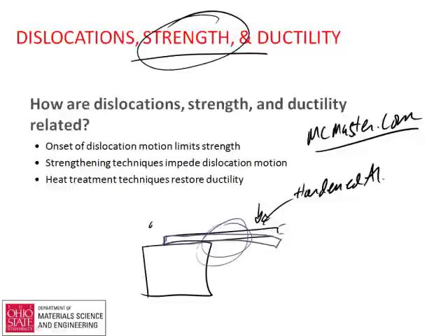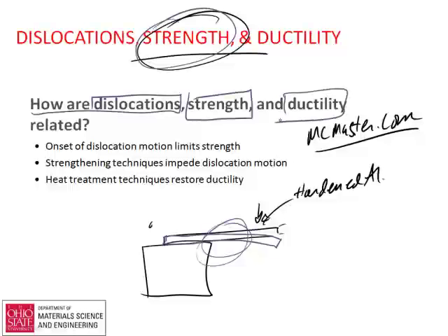The material would be very weak, but it would have the same stiffness, again showing you that strength and stiffness are controlled by different things. And again, what we're going to talk about today is what controls strength. And strength is controlled by the motion of dislocations. We'll talk about what dislocations are first, show how that gets into strength, and then I'll mention a little bit about ductility, which we also mentioned last time, which is how far something can stretch before it breaks.